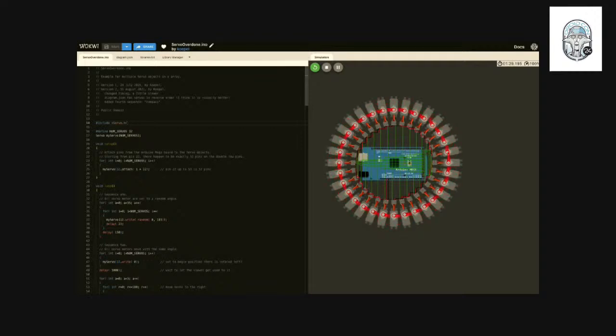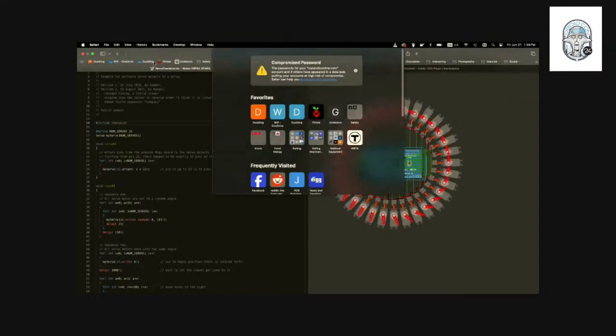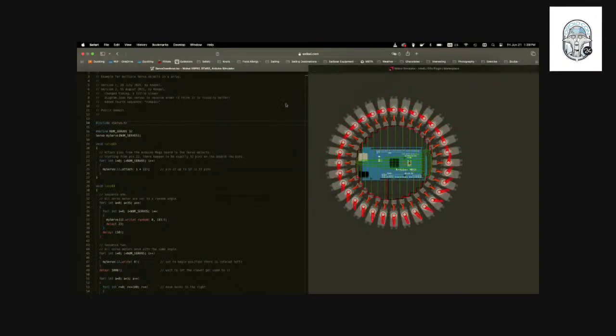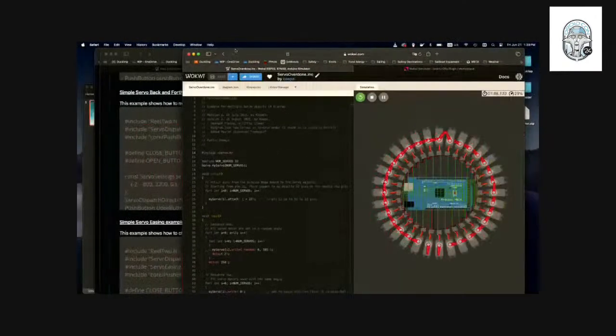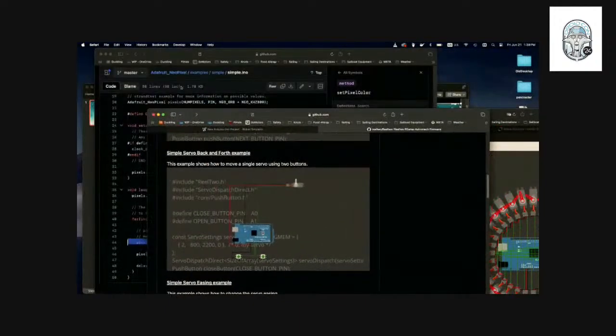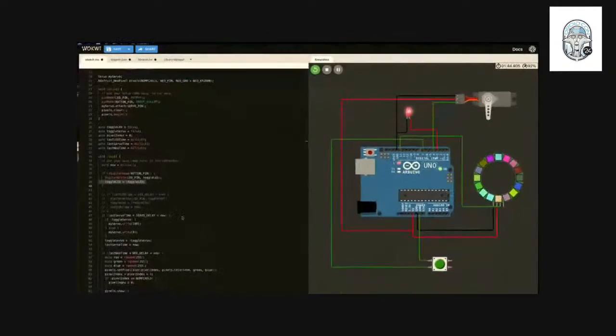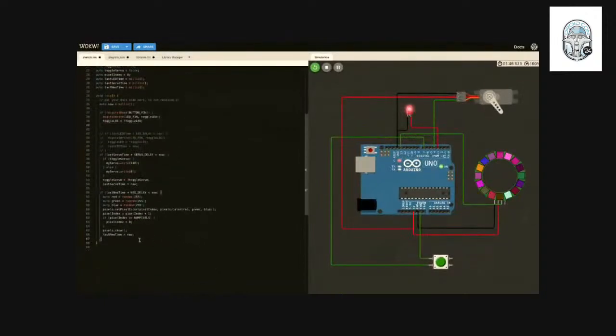So for people that are new to Arduino, can you explain why it's important to reduce or hopefully eliminate the use of delays in your routine? Right. So you saw that earlier in our simpler example there, that if we just had the delay here at the bottom, it prevented, say I put a delay here to 1000.